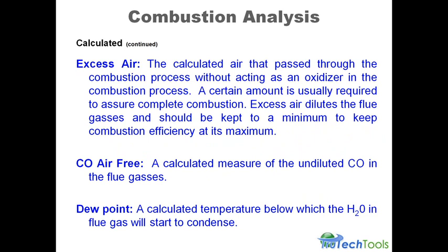Well, the problem with that is it doesn't tell us how much CO there is. If all that gas went into the space, the same volume of CO would go into the house as it was before, and obviously that's going to cause the same problem. So we went to a CO air-free measurement, which is apples to apples. If we take the oxygen dilution out of the equation, how much CO is actually in the air? This is the one that we care about. This is what all the standards are written on.